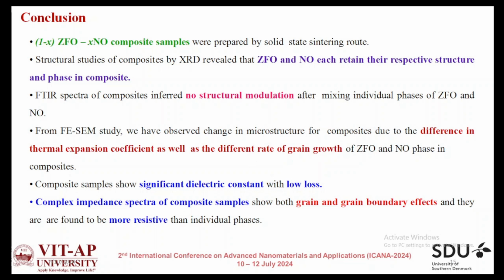And composite samples show significant dielectric constant with low loss. And we have studied complex impedance spectra, and the composite sample shows both the contribution from grain and grain boundaries, and they are found to be more resistive than individual phases.